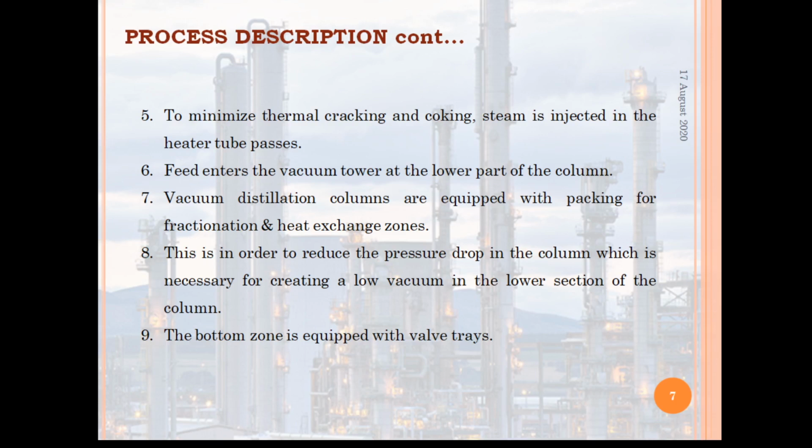So in that section we need to provide that packing inside this vacuum distillation column, in order to reduce the pressure drop. This packing is provided in the fractionation and the heat exchange zone to reduce the pressure drop in the column, which is necessary for creating a low vacuum in the lower section of the column.